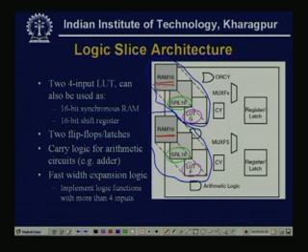So, actually, this is a lookup table. How is it implemented? That means this lookup table has 4 input bits, and then there is width expansion logic, so you can implement logic functions with more than 4 inputs.